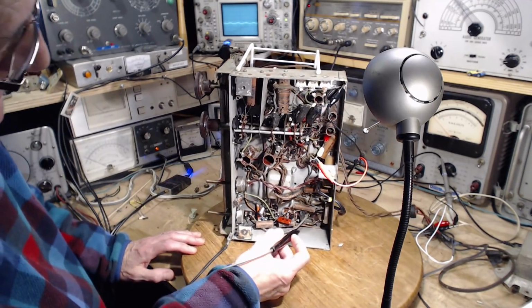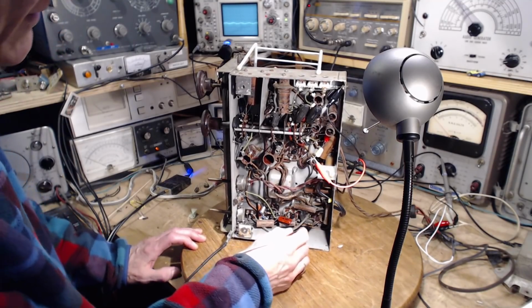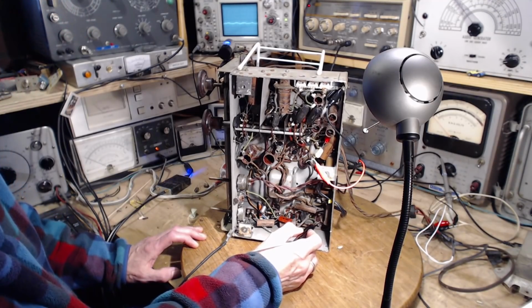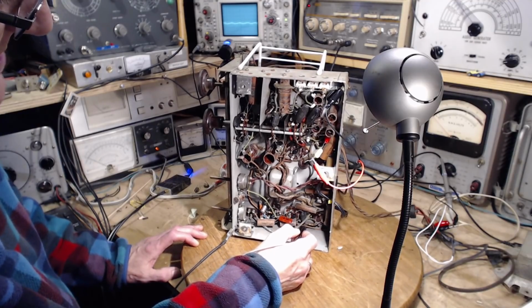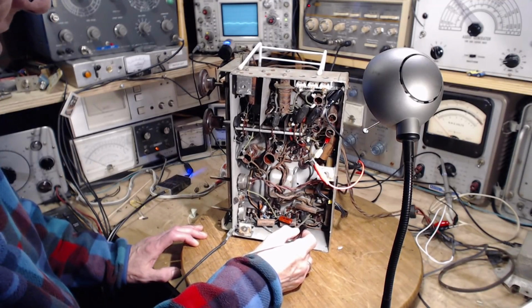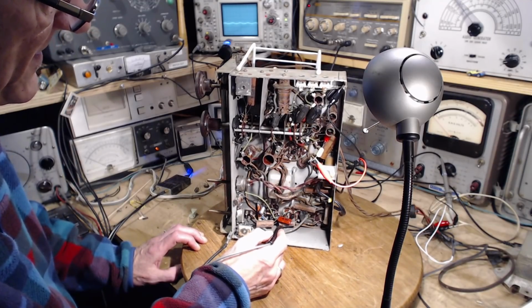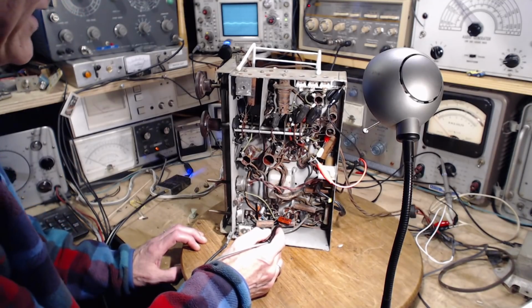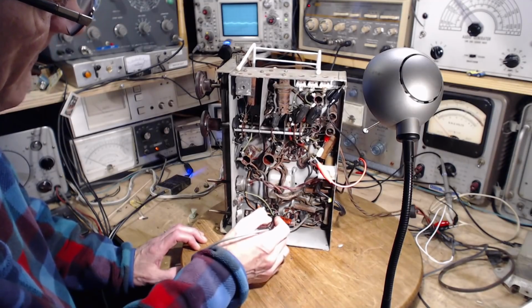Probably, let's see, to this pin where there should be voltage. I see a resistor here. 470. What's on the other side of that? Hey, lots of voltage there. But on this side, nothing. So this capacitor could be shorted. That would be a bad thing. I mean, that resistor would be pretty hot, probably.